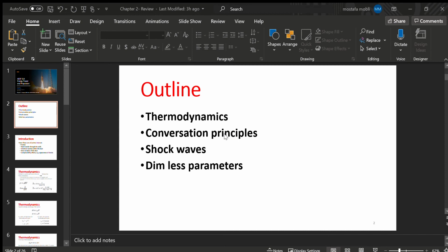Is the link here clear? Just move T to the other side, and dE and dH are CvdT and CpdT, right? Just plug them in here. You will end up with these equations, which are the main equations that help you calculate the entropy or changes of entropy in a system between two states of the system.